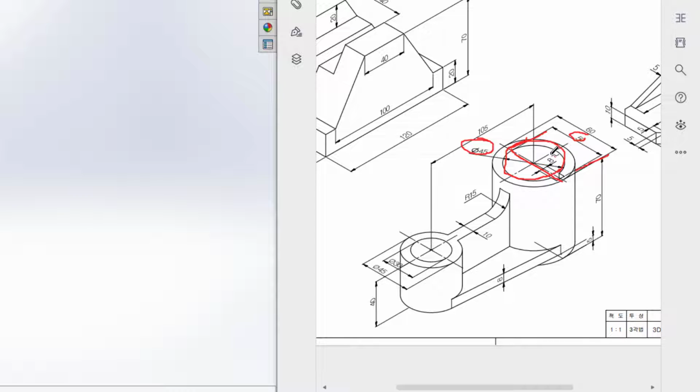Then we can see the total distance is 8 unit. I'll draw two offset lines of total distance of 8 units, so it will be I think 4 by 4. Okay, then I will close the shape. Then finally the shape will look like this, this circular portion, and then this key shape. Okay, then I'll extrude cut this total portion.